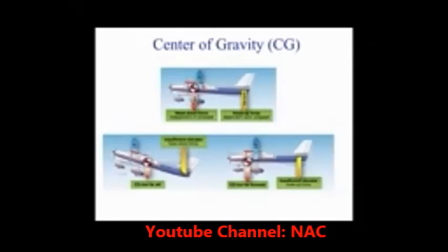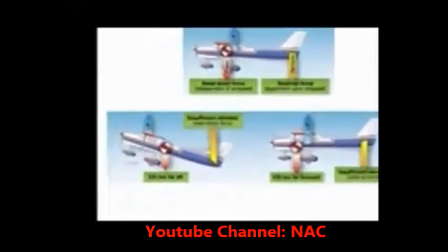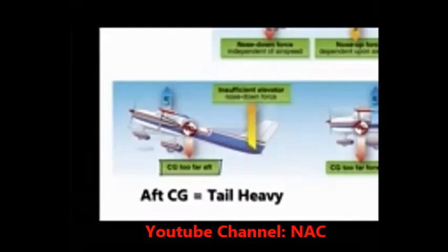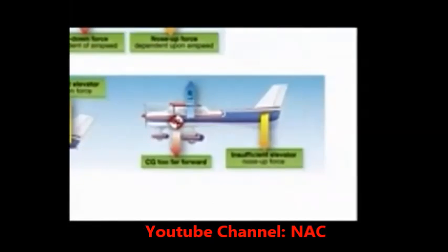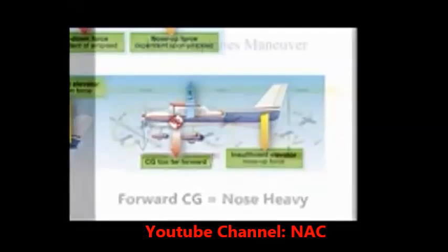The position of the center of gravity is very important for aircraft and can be affected by the installation of onboard equipment, aircraft loading, and other factors. When the center of gravity is too far aft, or too far towards the rear of the aircraft, the plane will have a tendency to pitch up, which can cause the plane to stall. While having the center of gravity too far forward, the plane will have a hard time getting off the ground, and the nose will tend to pitch down.